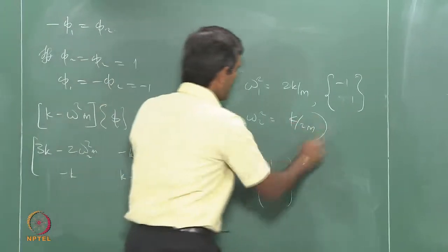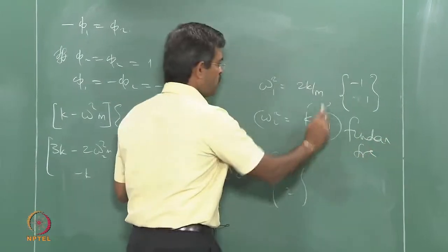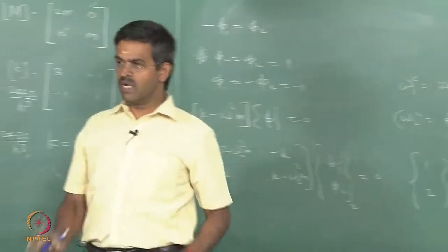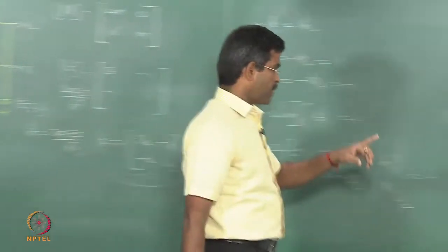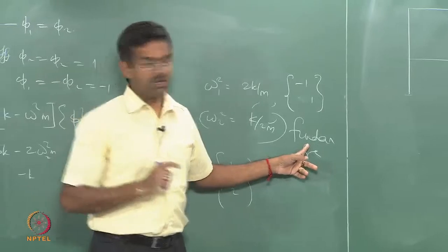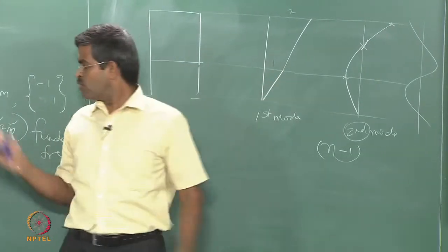So, I can call this the fundamental frequency even without knowing the values of k and m. That is very, very important to understand. Characterizing the fundamental frequency should be based on the deflected shape or the mode shape of the system, not on the numeric value alone.